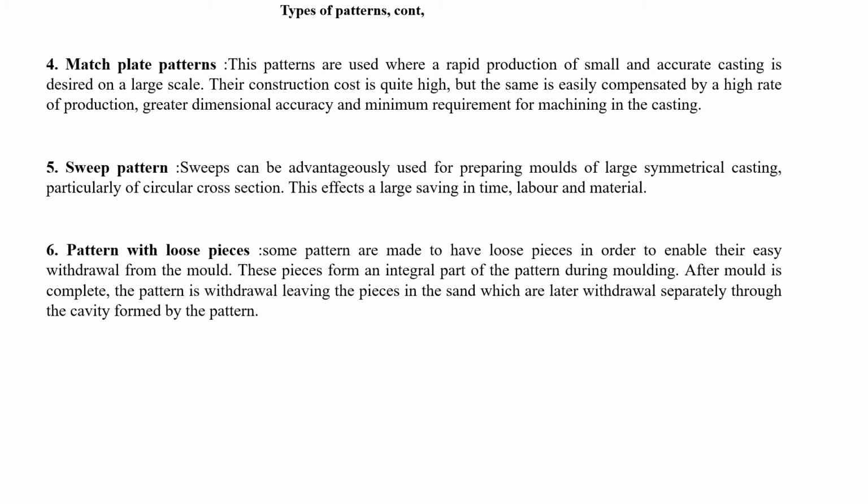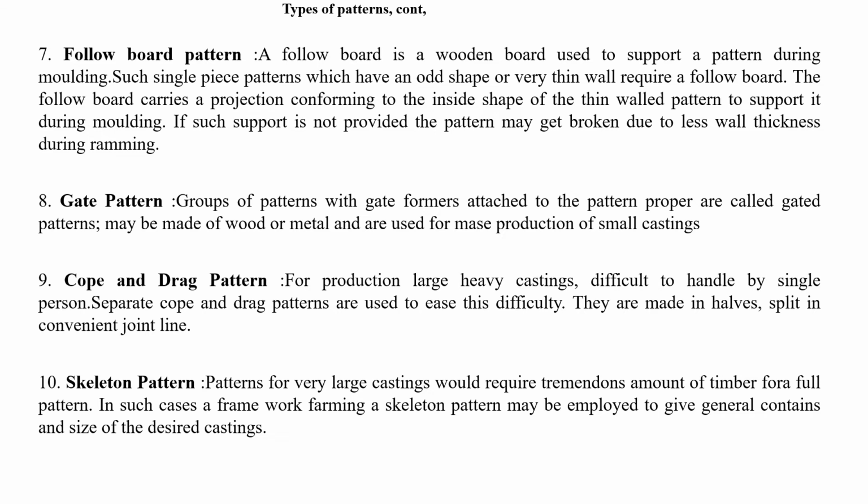We have also the pattern with loose piece. This one is equipped with a loose piece, which helps with withdrawal of the piece. And then we have the follow board pattern. This one is used when a very thin piece is required.